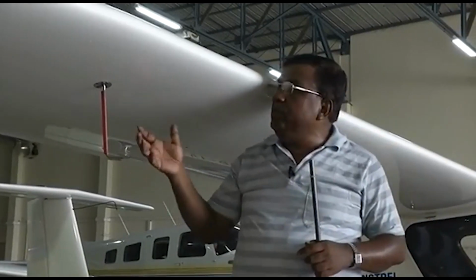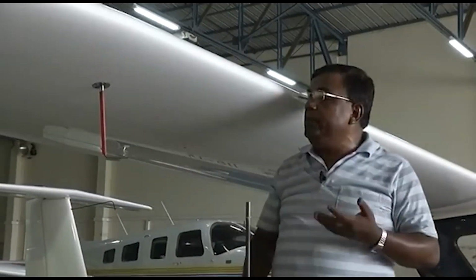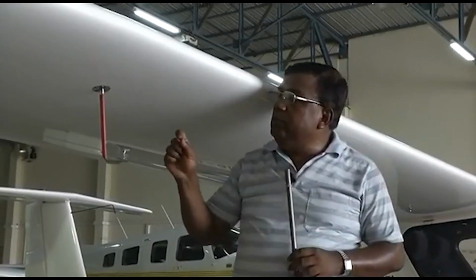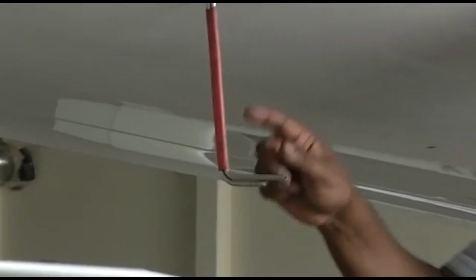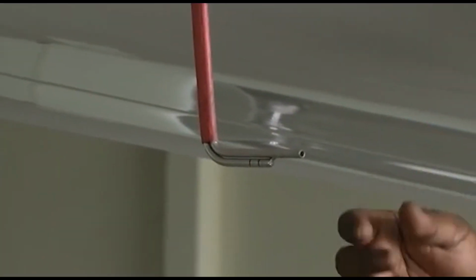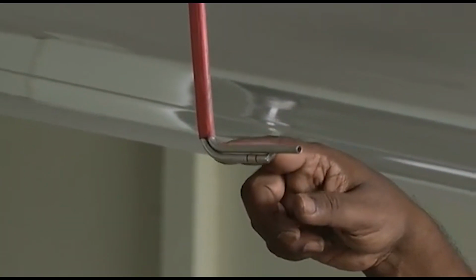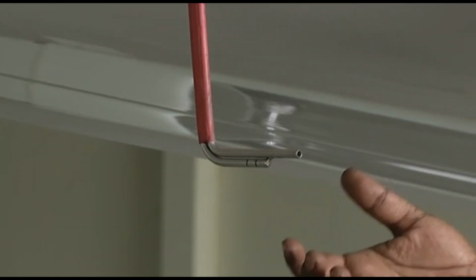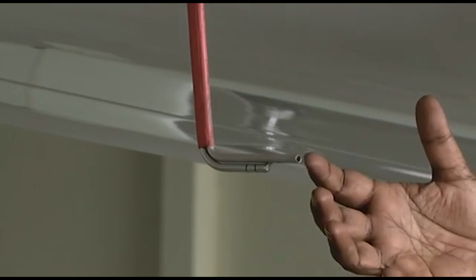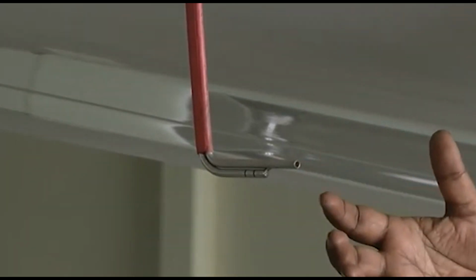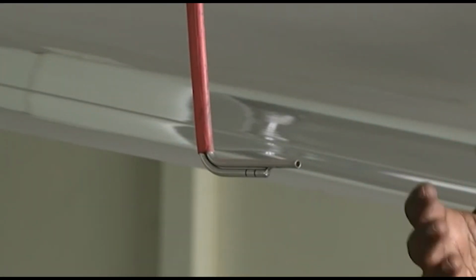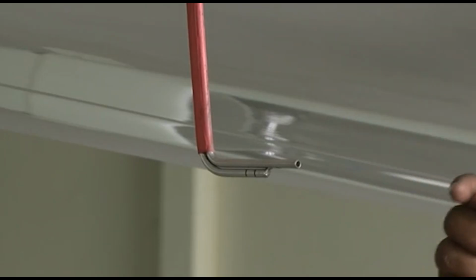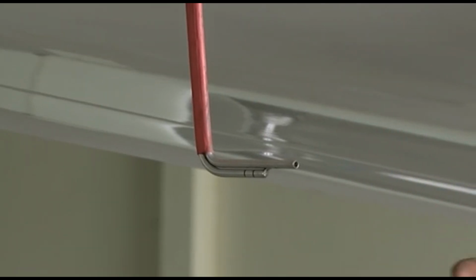Okay? It needs some calibration, but the important thing is, before you go for flying, you need to know what the speed is. For a pilot, speed is extremely important. So one has to be doubly sure that the Pitot tube is working. Sometimes what happens, some insects may lie inside this Pitot tube and you may actually get a wrong value. So a very, very dangerous situation. So any pilot, before he takes off, despite the engineer's clearance, will check whether the Pitot is working or not. Okay? In addition to other control surfaces.